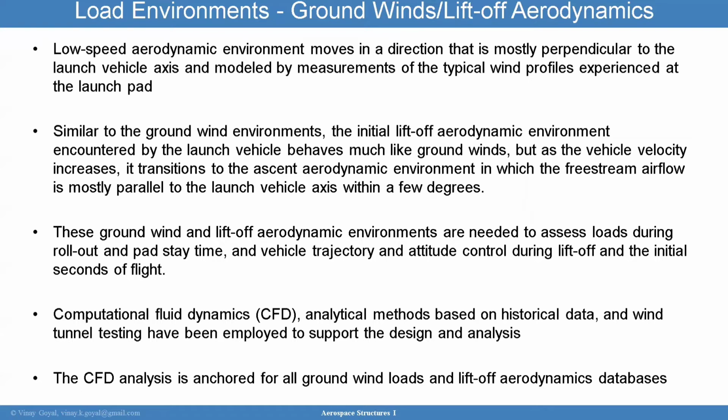Similar to the ground wind environments, because this is the ground wind environments I'm talking about, the initial liftoff aerodynamic environment encountered by the launch vehicle behaves a lot more like a ground wind. But as the velocity of the vehicle increases, it will then transition to an aerodynamic environment. In this case, the free stream airflow is mostly parallel to the launch vehicle axis. But you can see how, as the vehicle is stationary, the ground winds that are perpendicular to the launch vehicle axis start to transition to more of an aerodynamic loading environment.